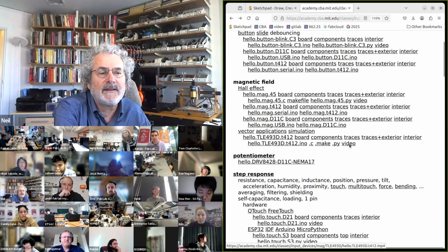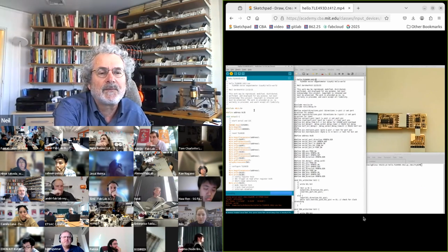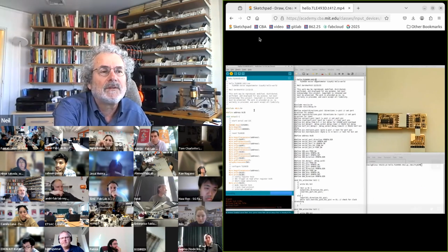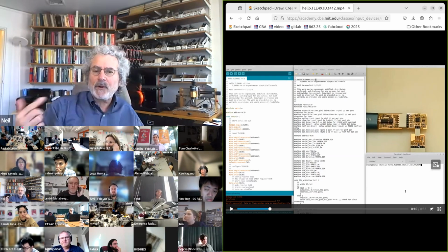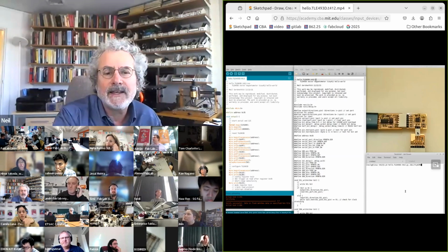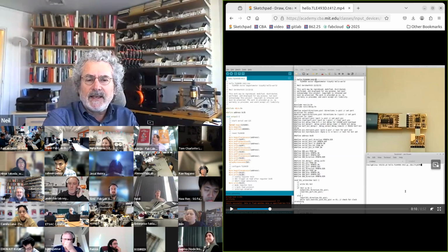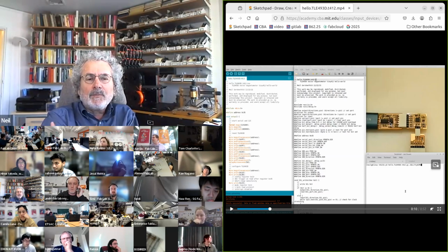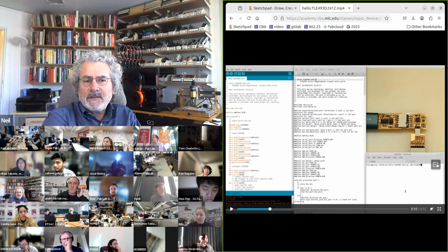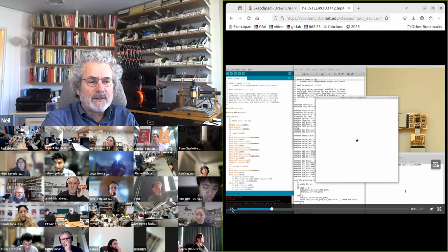And then here's what I can do with it. First, just to explain this image, here's my project. For the Tiny 412, you program it over UPDI. And you can do that with a simple serial interface. So this is a UPDI programmer. And then on this side, I've got a serial port that converts TTL serial to USB, which is why you see three boards.